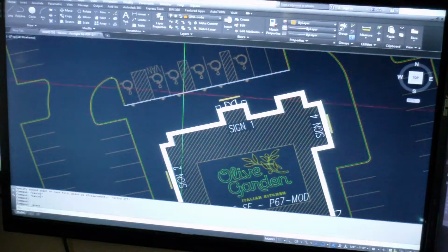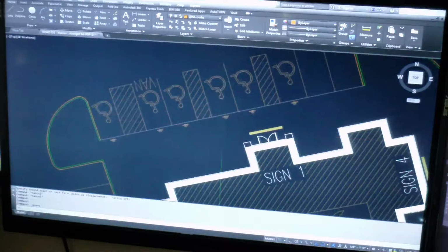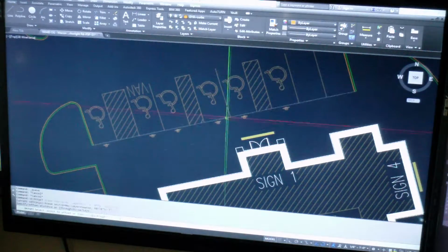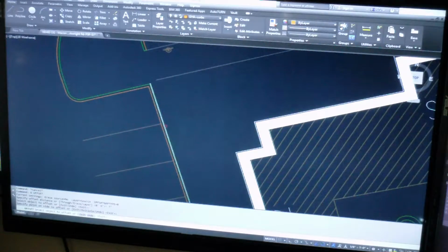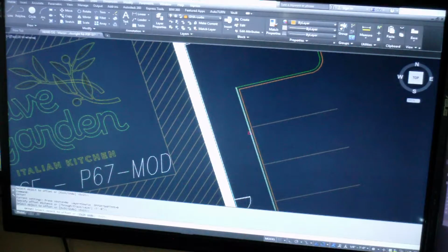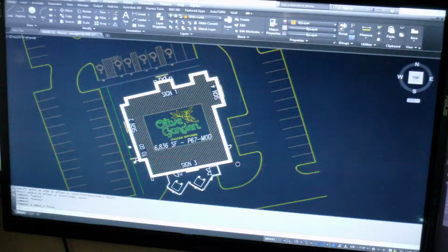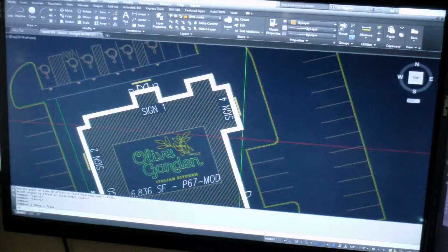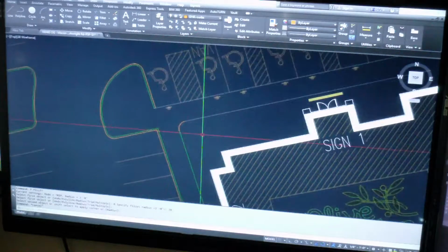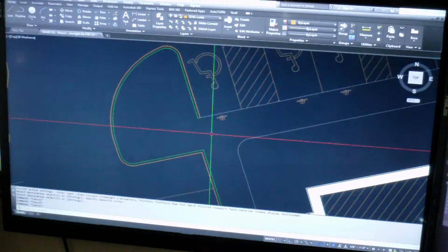Alright, since this sidewalk is going to be in front of a row of parking, I'm going to make it 7 feet wide. Same thing on this, 7 feet wide. This one's getting pretty close over here, so I think I'll probably just make that whole area right there sidewalk. That's not what we really like to do very often, but we'll go with it this time. Just match all this, put it all on flat work.